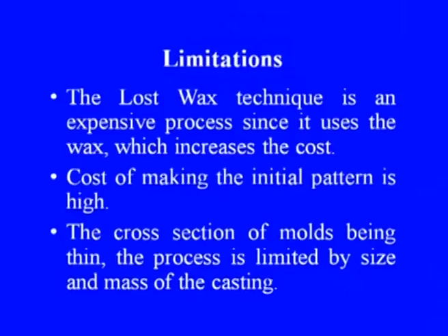Now, let us also see the limitations of this process. The lost wax technique is an expensive process since it uses the wax, which increases the cost. The cost of making the initial pattern is very high. The cross section of molds being thin, the pattern is limited by size and mass of the casting.